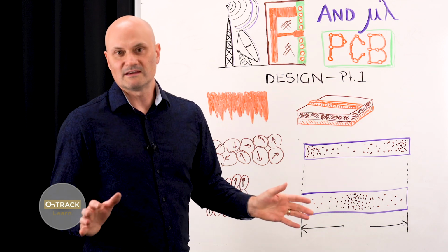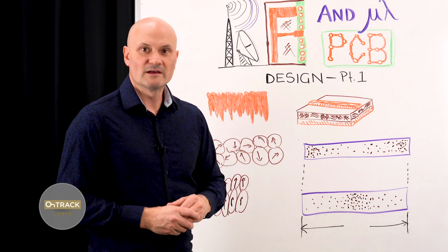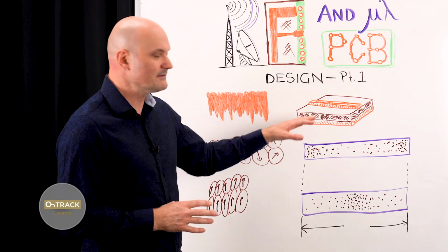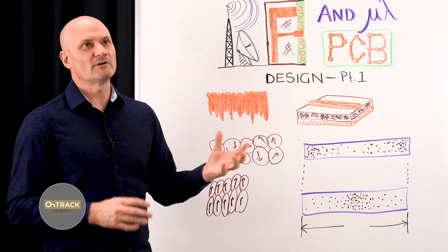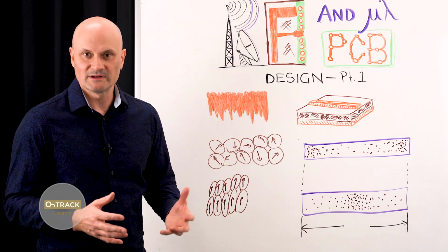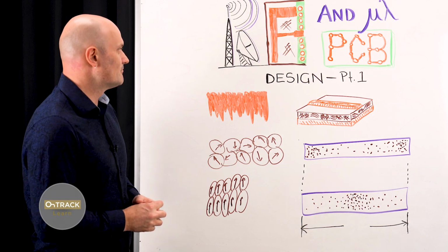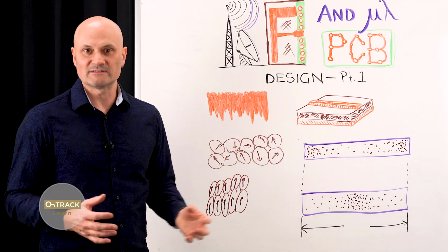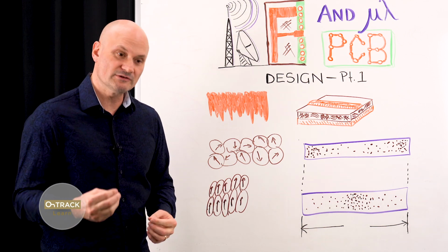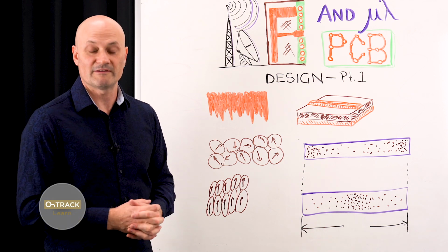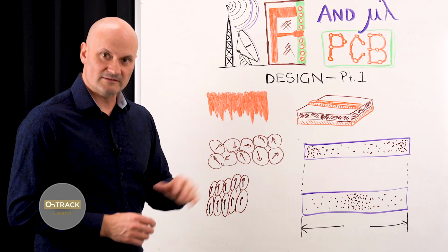The substrate is usually a combination of epoxy or some kind of thermosetting plastic material, typically reinforced with glass fibers, almost always. Some older or cheaper boards use paper, like paper phenolic resin for FR1, and for the most part recently, FR4 is the most common, cheaply available material, and you can actually do some RF design on a typical FR4 PCB, but you need to know what's going on. So first, let's talk about conductors.